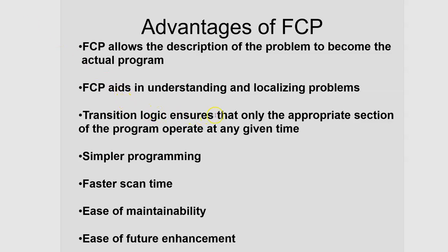Transition logic ensures that only the appropriate section of the program operates at any given time. We've already mentioned that. That can save scan time. I skipped this one. It says it aids in the understanding and localizing of problems, so it's easier to troubleshoot. If you understand how each mini program works, each step, then if you have some kind of issue, if you really understand the system, it's easier to isolate the problem.